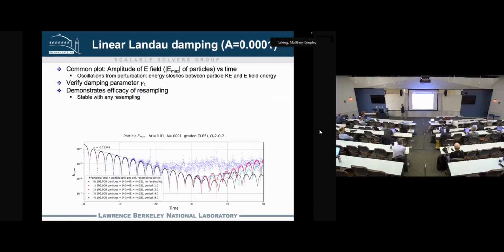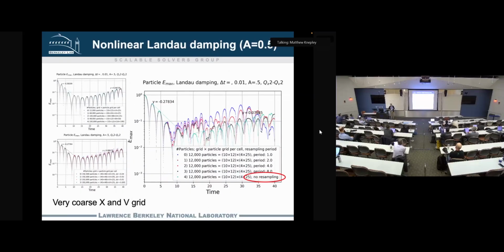Now, if you had a perfect model of this, very well resolved and so on, the damping would just go to 0. But the subgrid modes will start to develop unless you have an extremely fine grid, and you get this kind of a rebound where it'll hit and then it'll come back up and do various things. I'll show you some more plots of that. So this is a very common pattern.